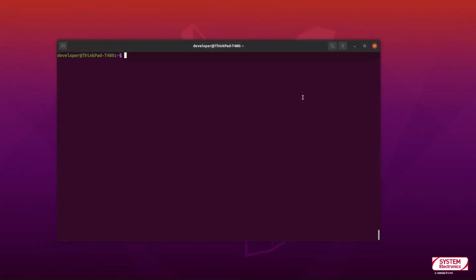Here comes the software part. First, connect to your Astrial board using SSH. Replace the IP address with the IP address of your device. Alternatively, you can use Astrial directly with a keyboard and mouse with an HDMI monitor. Now that we're connected to our Astrial, let's install the GPIO library using pip3.